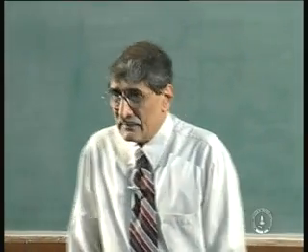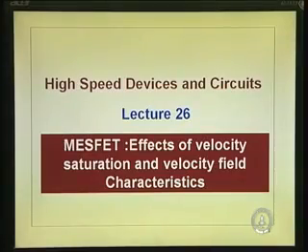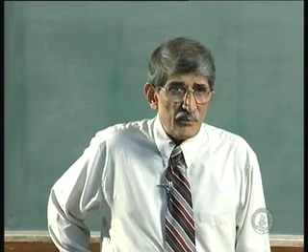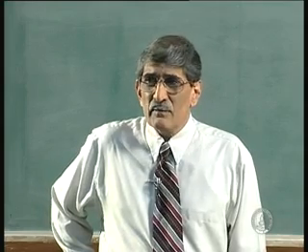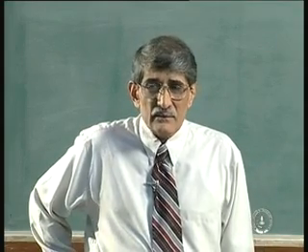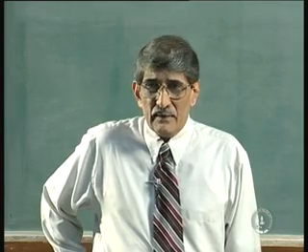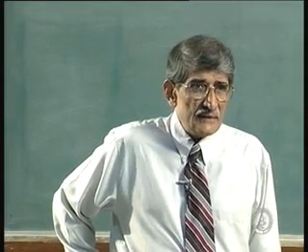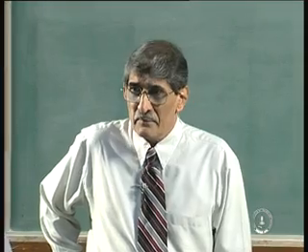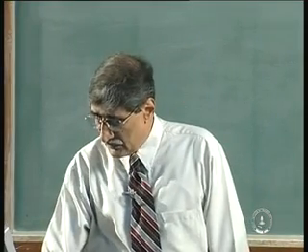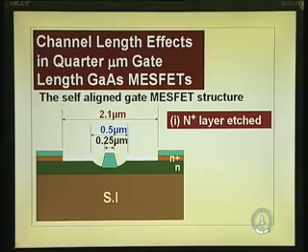So, we have been discussing the MESFET characteristics, taking into account the velocity saturation, and we have analyzed it. Finally, we were comparing some of the experimental results that people have reported. One result that we saw was the change in the gate length. There we saw the pinch off voltage changing unless you change the thickness. Then we took a look into the channel length effects.